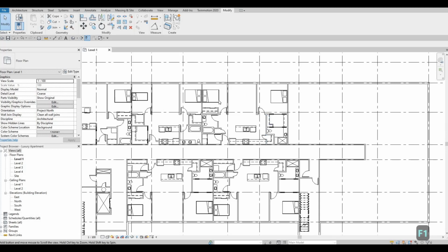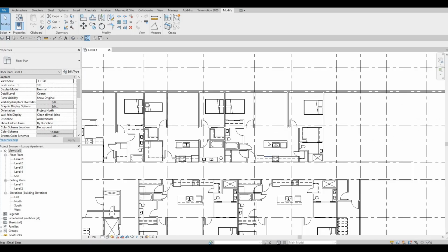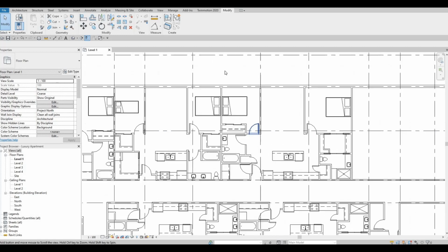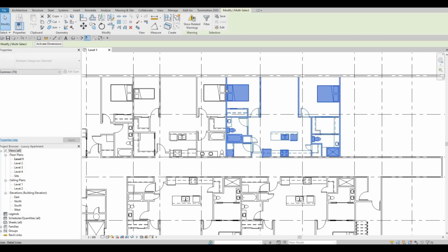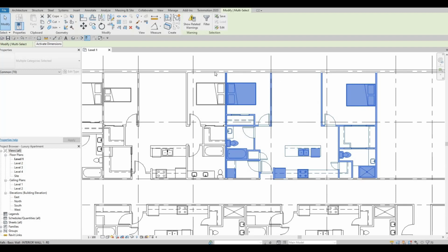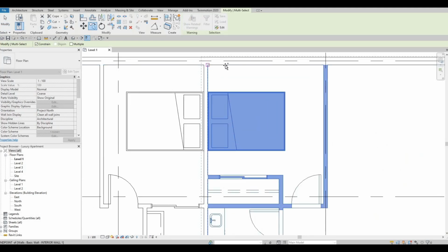So the good thing here is we could just copy this wall or this suite because it's the same as the one on the right side. Just don't copy this one, but grab it from that corner. So copy and then click on that.